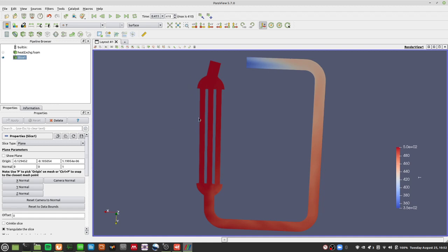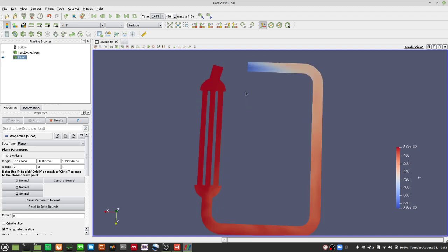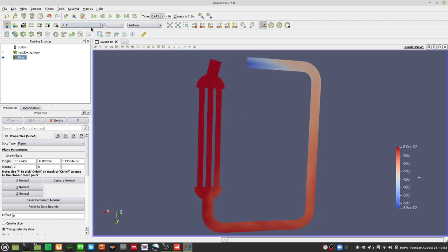So we kind of need to increase the cooling over here and change this into a proper heating up boundary condition rather than a cooling down one. So I probably have to change the sign convention to something like minus 80, for example, and that should about do it. Okay, so this is the heat exchanger results. On the whole, I'm pretty happy. Just need to change a few more boundary conditions, but the stability speaks volumes for itself.